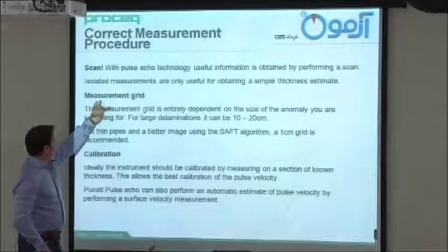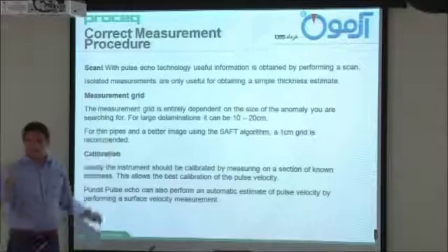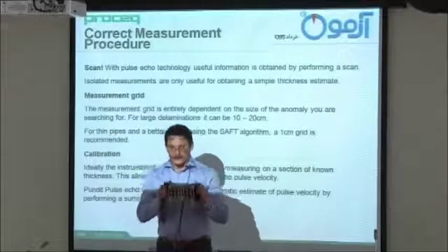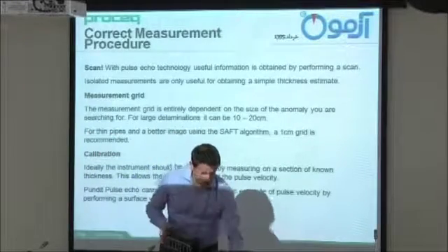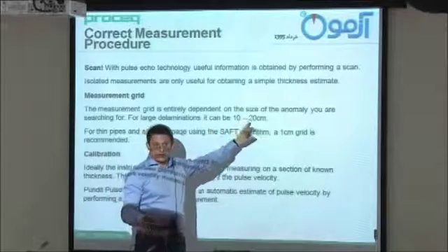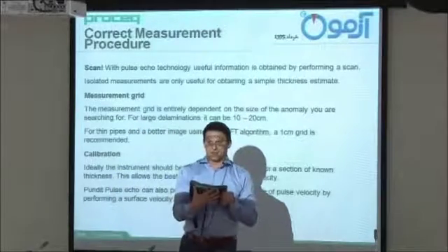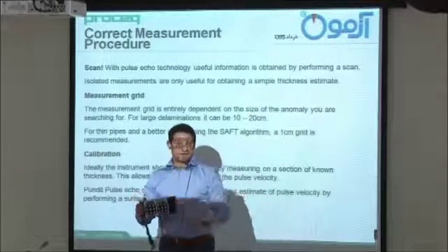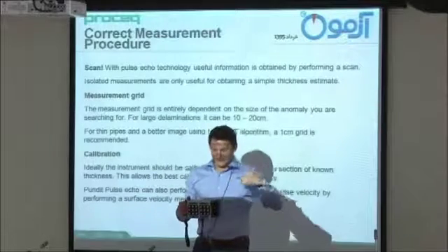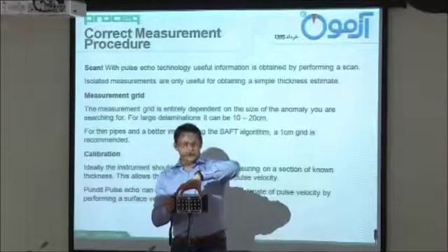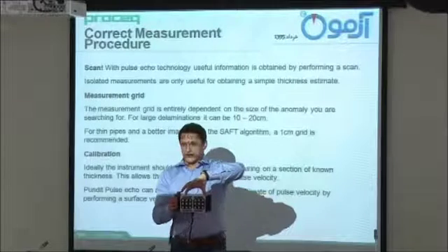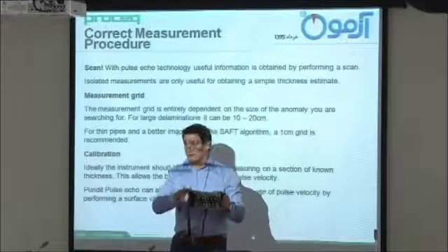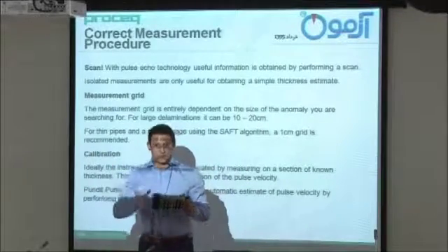So this is more or less to use. And the good thing is to know, especially when you do big projects with the measurement grid, we don't have a roll, you have to go step by step. So here you can read 10 to 20 centimeter. This is approximately 15 centimeter. So if you step 20 centimeter, you will have a gap. It's okay. I prefer from the technical side that I just use more or less 80% so that I overlap for 2.5 centimeter.